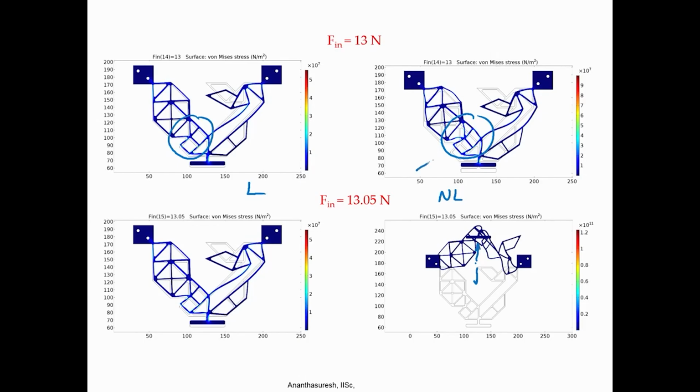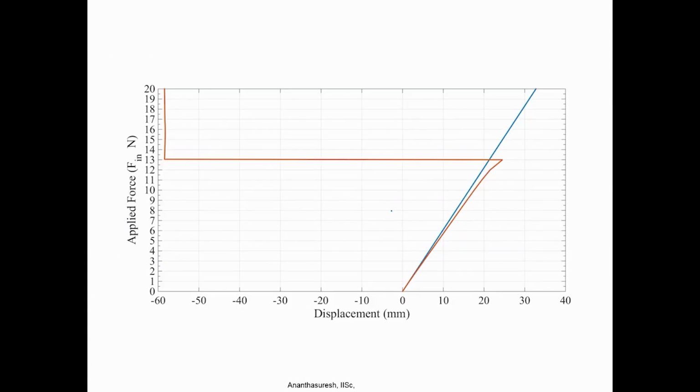We can see the signs of it at 13 newtons, just a little bit. Anything that happens suddenly is a catastrophic phenomenon, that is how buckling occurs. And that is what we saw in the deformation behavior over here. As we increase the force, at some point displacement changes direction and goes to a very large value, as shown there, and that will be captured only in nonlinear analysis.